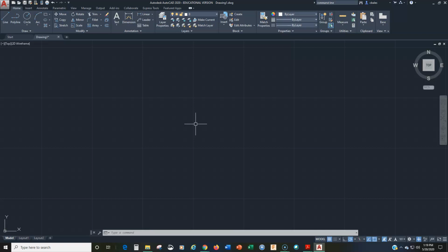So that means that in this area we always want to draw without scaling. If we're drawing a battleship, we want to draw it with battleship dimensions. If we're drawing a nano machine, we want to draw it with very small measurements. And then we zoom in or zoom out to show us the detail that we need in this environment. Okay, so that's the drawing environment.